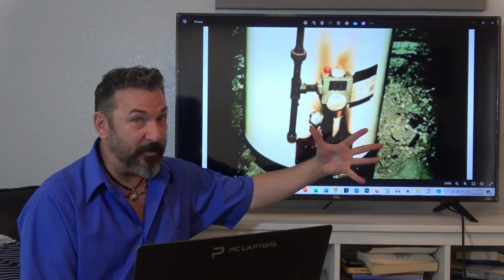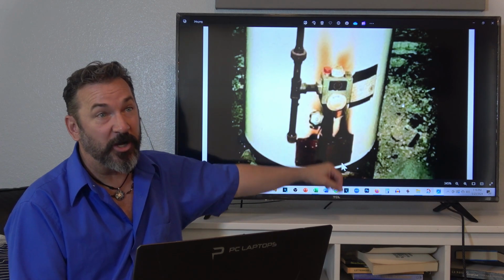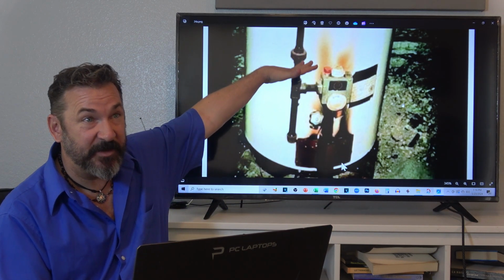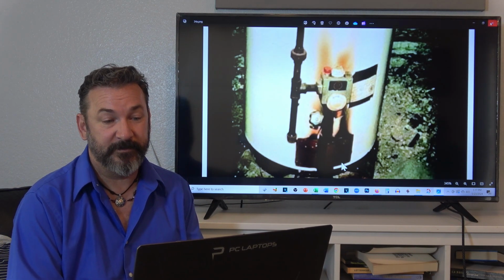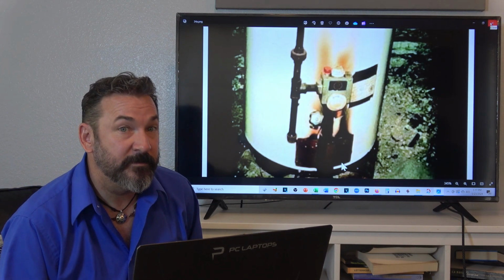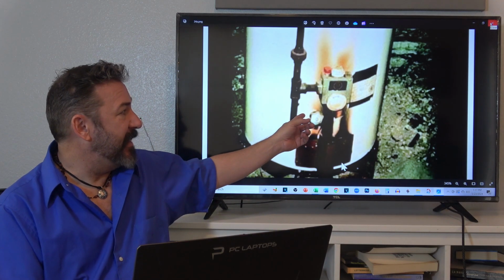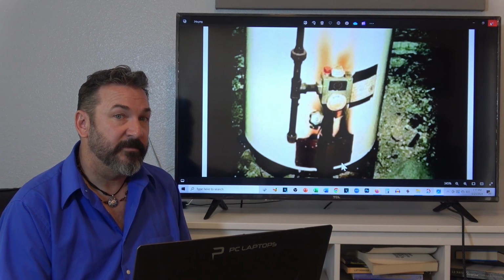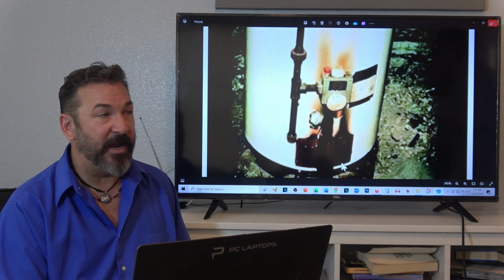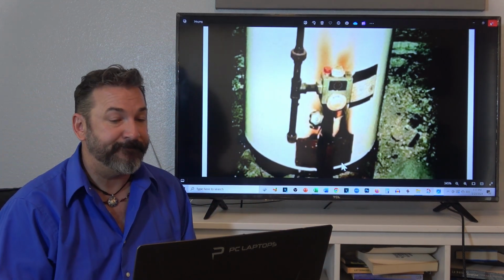The flame will just burst right out, and that means it's been doing it for a long time. There's some consistent back pressure. That's a backdrafting water heater, so that doesn't have to do with the blower or leakage. That's from the gas, from the combustion. There's not enough combustion air in that area, and it's not drafting out. It's got some sort of back pressure on it.